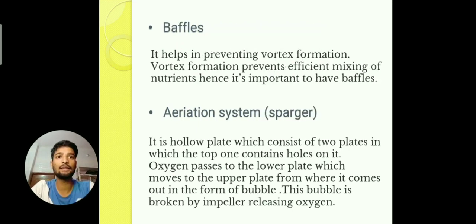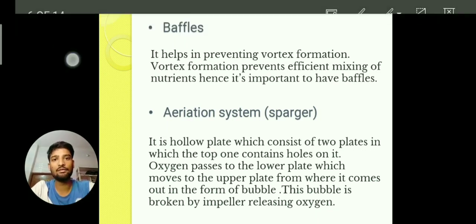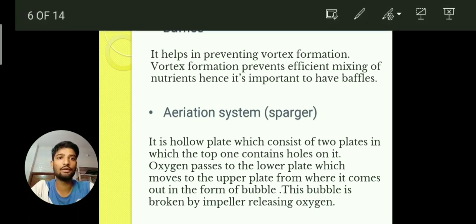Baffles. They help in the prevention of vortex formation. Baffles are side mounted walls which help in the prevention of formation of a vortex. A vortex can be defined as a tornado which gets generated inside a fermenter. So baffles help in the prevention of formation of a vortex. In simple words, we can say that